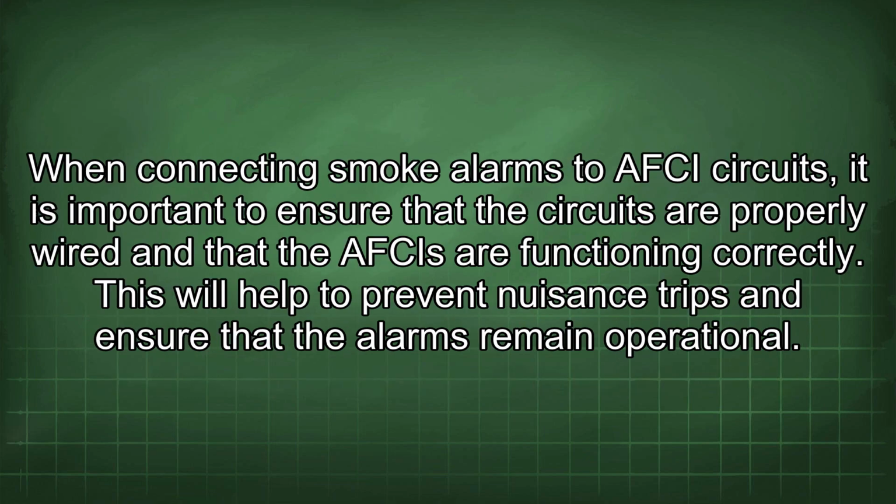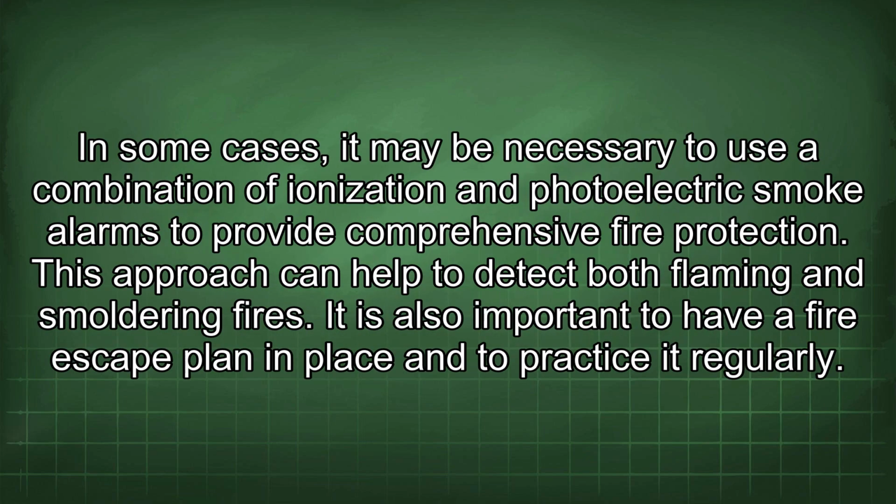When connecting smoke alarms to AFCI circuits, it is important to ensure that the circuits are properly wired and that the AFCIs are functioning correctly. This will help to prevent nuisance trips and ensure that the alarms remain operational. In some cases, it may be necessary to use a combination of ionization and photoelectric smoke alarms to provide comprehensive fire protection. This approach can help to detect both flaming and smoldering fires.